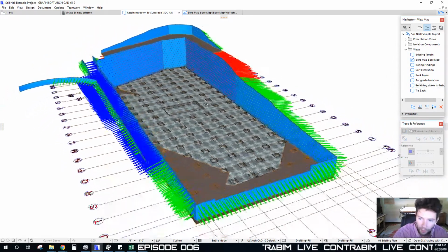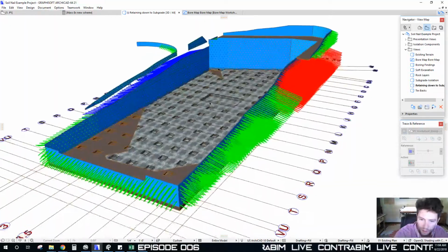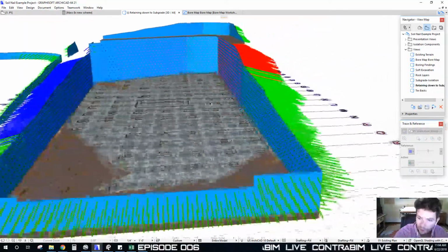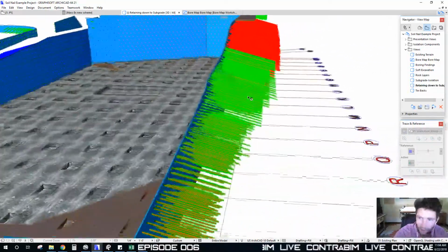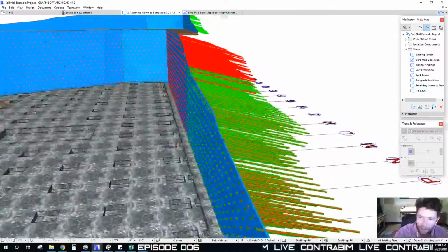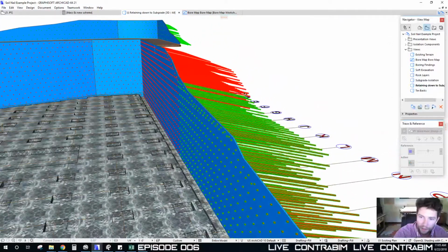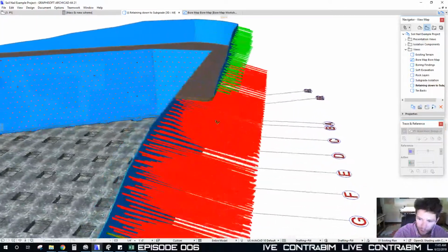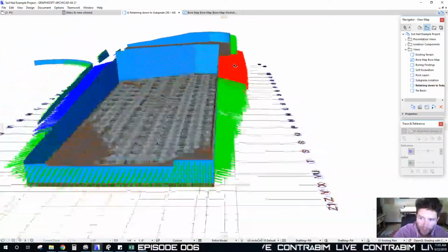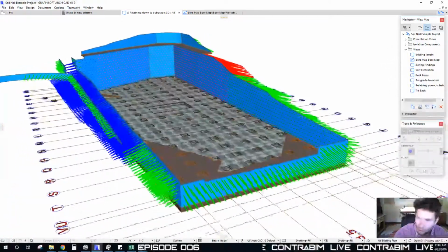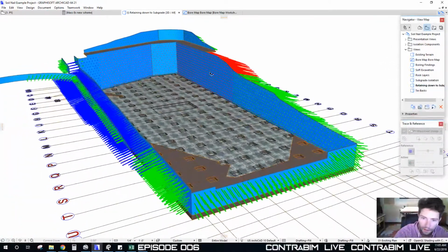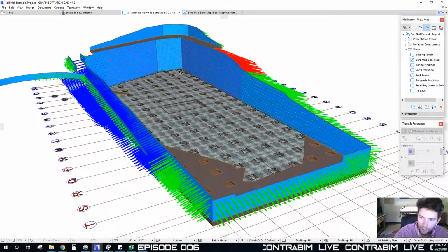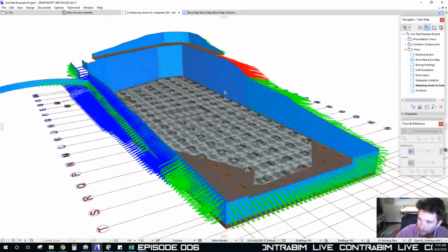This particular project is an example of a soil nail type retaining system, where you're nailing in and not having an active tension put on those elements, but just using the friction of the ground to maintain that soil stability. The other type that we're going to be looking at is a tieback type with the shoring and soldier pile, and we'll take a look at that here in a second.